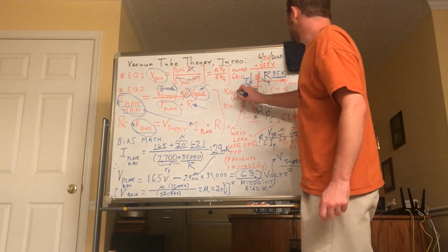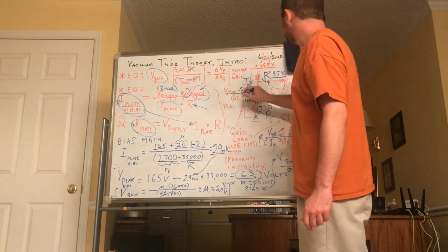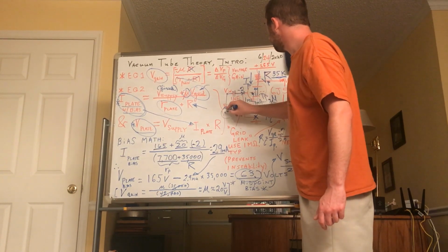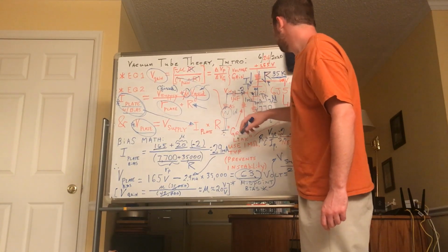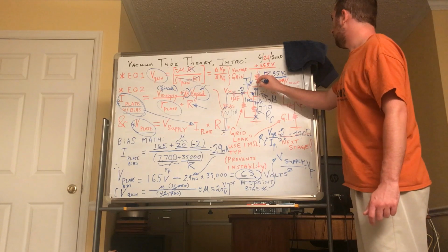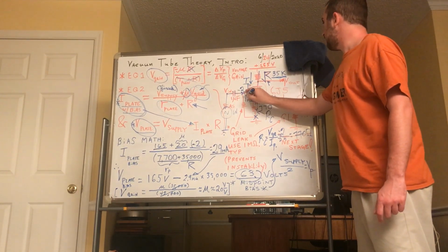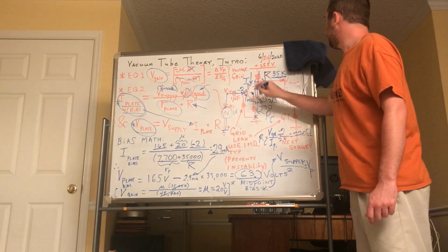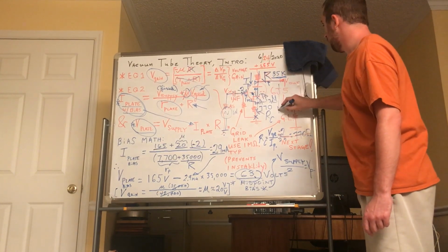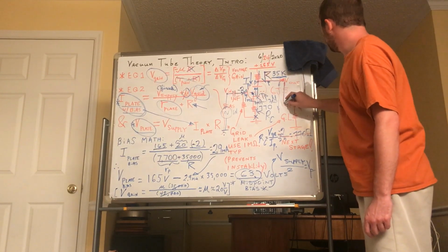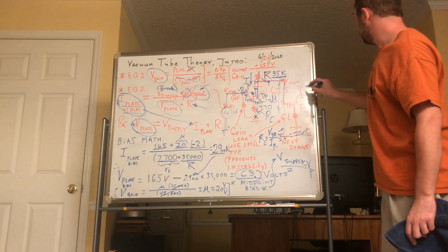Now, of course, you would put a coupling capacitor here, making a high pass network, and then your input voltage would go here, just like this, Vin. And then your output will be taken across the plate. And again, this is your cathode K, your grid G, and your plate P for this triode, 6J5, and your output voltage would be between here and ground. But in practice, it could be capacitively coupled to another amplifier stage, as shown here, and this could be another 6J5.